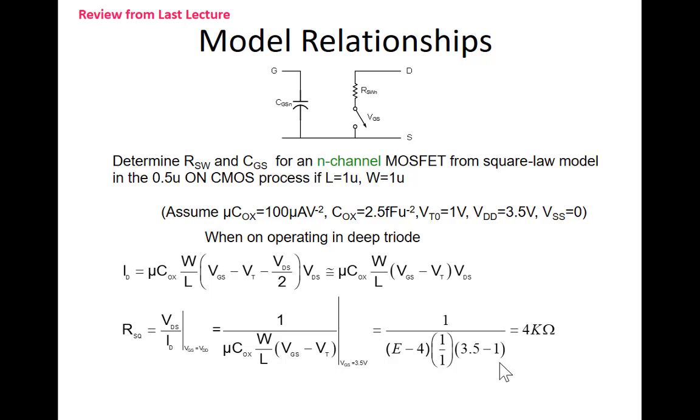So in our earlier switch level model of the device, we said, let's assume that the resistance of the P-channel device is so much and the N-channel device is so much, right? We didn't say where it came from. We know what it is in this process. What did we use before? Earlier in the course, 2 kiloohms, 6 kiloohms. 2 and 6. So we said for this process, it's more like 4. Make sense? So different processes will have different values for the switch resistance and the capacitance, CGS.